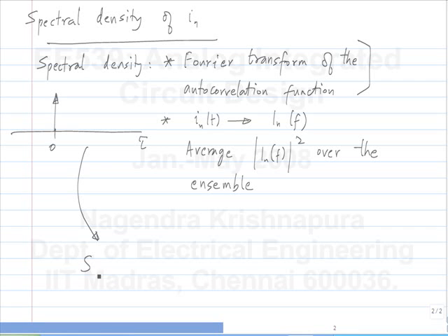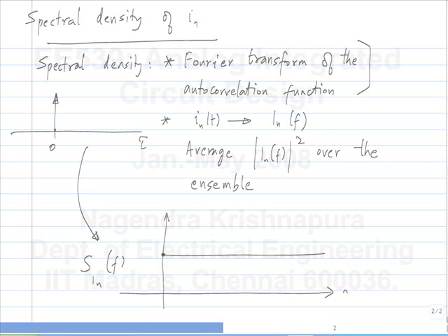So the spectral density of Y is a constant with frequency, and typically in circuit analysis we use single-sided spectral density, that is, we plot only for positive values of f. All the signals we are dealing with are real, so you can always use the double-sided spectral density, but we choose to use single-sided because it is symmetrical about 0.